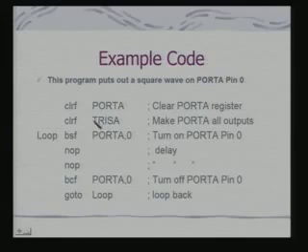In this case, we use a register called TRIS, and since we are talking about port A, we have a TRIS A register, and we are clearing the TRIS A register, making all pins of port A output pins. Here again you can see a usage of the clear instruction for doing hardware programming.